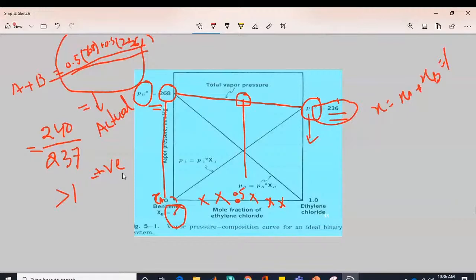Disadvantages of vacuum distillation: persistent foaming occurs. That's one of the difficult things. This may be overcome by adding capryl alcohol to the liquid or by inserting a fine air capillary tube in the second neck of the glass flask. A stream of air is withdrawn and breaks the rising foam. The above method is not suitable for preparation of semi-solid or solid extracts by distillation under vacuum. Okay, so this was about vacuum distillation.